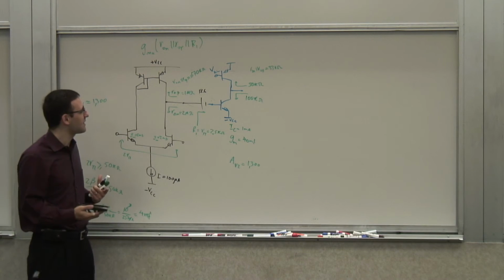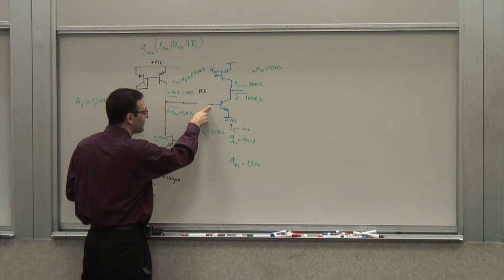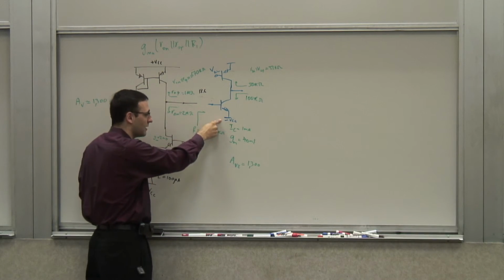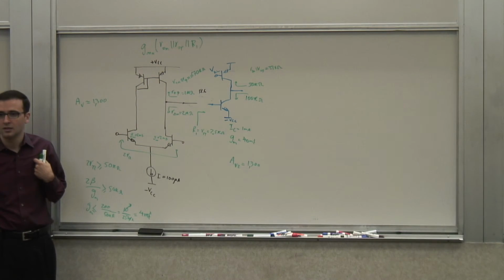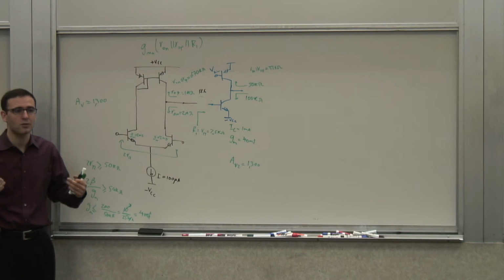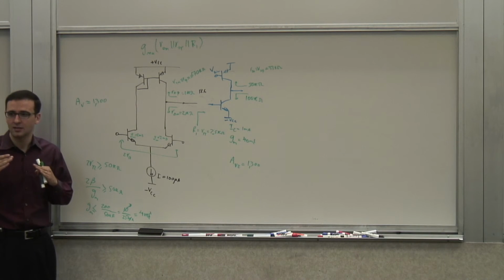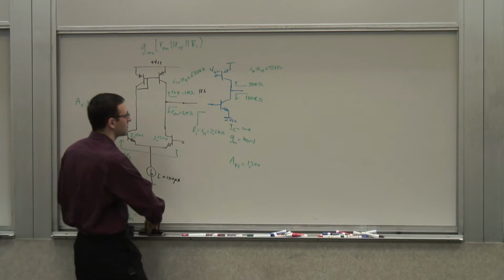The problem is somewhat fundamental because this guy references this voltage to, I'm sorry, not to ground, to minus VCC, and this guy is referenced to plus VCC. So the only way I can deal with this problem is what? If both sides were referencing that level to the same supply, either minus VCC or plus VCC, I don't care. One of the two.